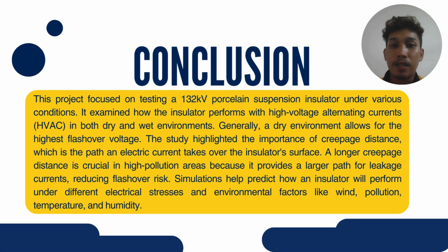A longer creepage distance is crucial in high pollution areas because it provides a larger path for leakage currents and reduces flashover risk. Simulations help to predict how an insulator will perform under different electrical stresses and environmental factors like wind, pollution, temperature, and humidity.